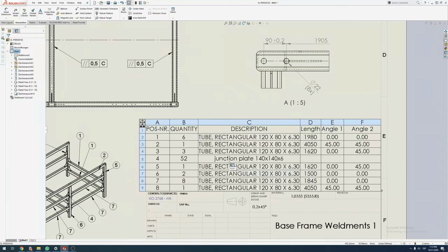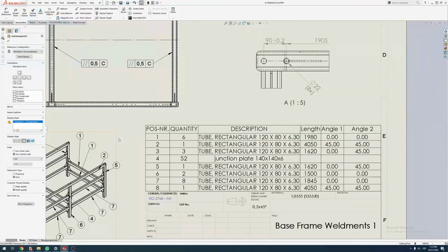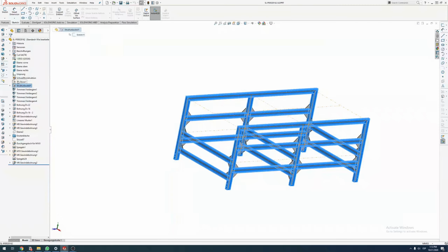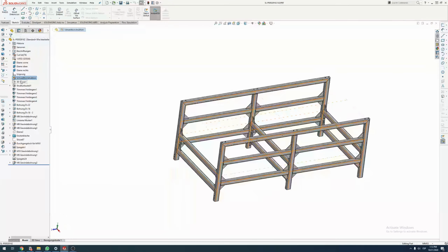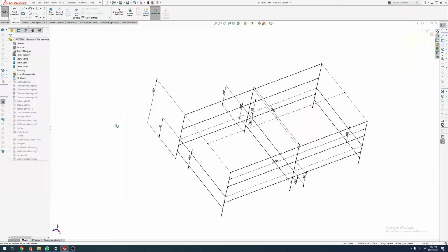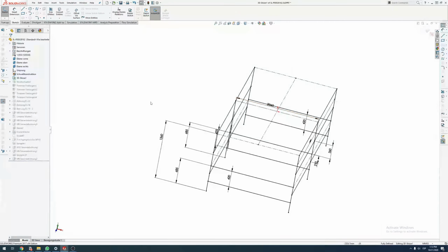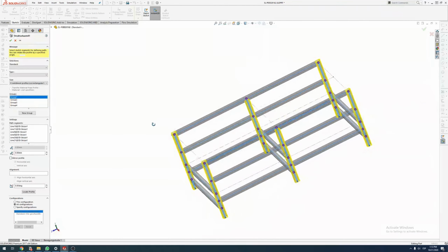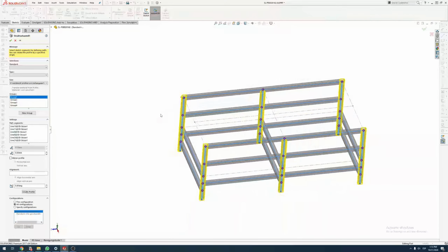You can, if you do the weldments correctly in SolidWorks, which means, yeah, it's a bit of a tangent, but it's relevant. If you do a weldment, and then you do a 3D sketch, and you define it, like this is a 3D sketch, pretty simple. And then you assign a profile, what kind of profile the beams should be made of, which you can define, and that's a completely separate video. It's very simple, very cool actually, the way it works.